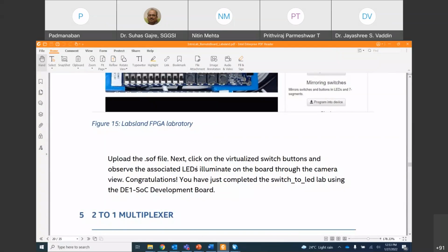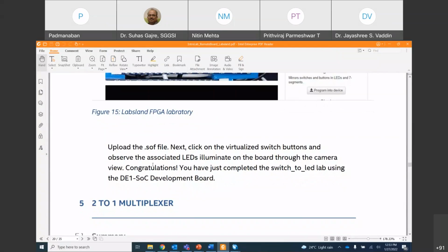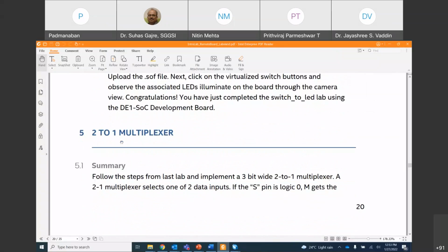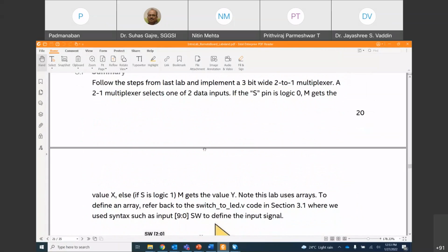entities. So I have done the first lab for you. I will share the lab manual with you, which has 2 more labs. One is on the 2:1 multiplexer, again a pure combo logic. And the other one is on the Night Rider, which is a clock divider code, where it will utilize the clock. So the only difference is instead of the other pin configuration, you should also copy the last Tcl command because it uses a clock for the design. This you can practice.